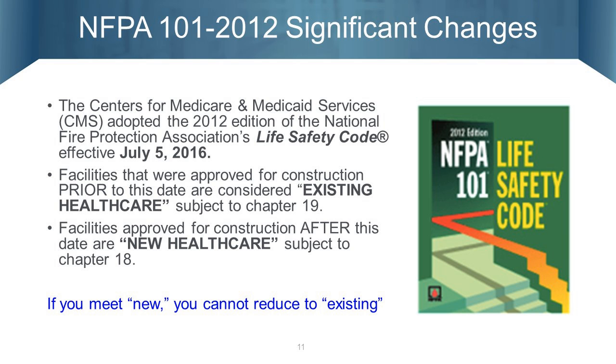Another thing to look at is on existing healthcare, a storage room or soiled utility room, if you're fully sprinkled, does not require the walls to go from deck to deck. Does not have to be 1-hour rated walls. They have to be smoke-resistive walls. And the door does not have to be 45-minute rated. It only has to have a closer on it and be a substantial door. So big, significant difference there too.